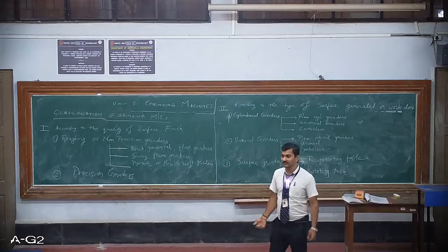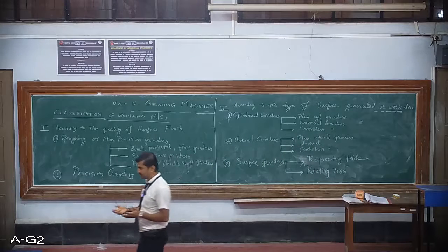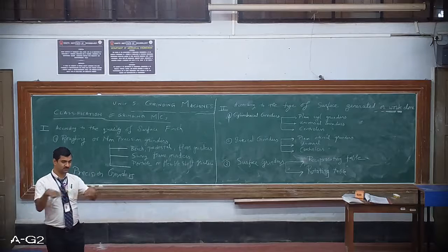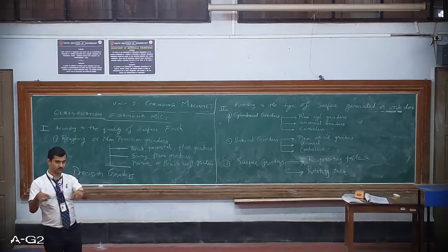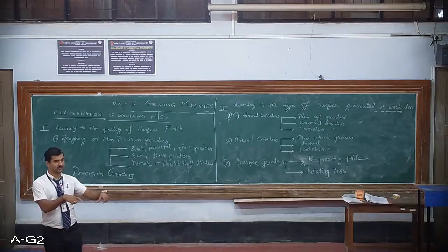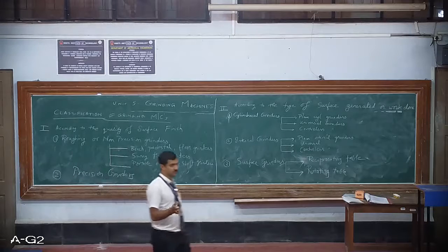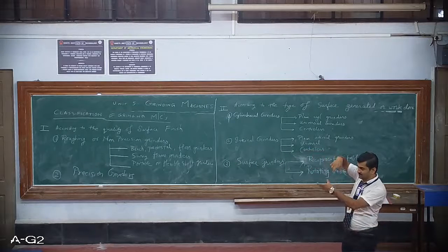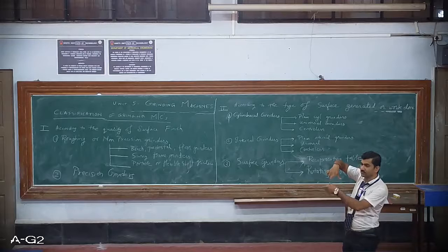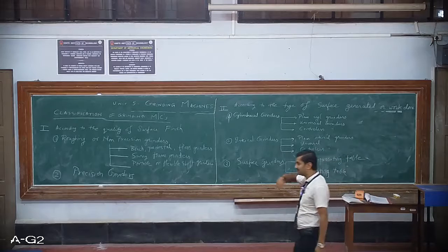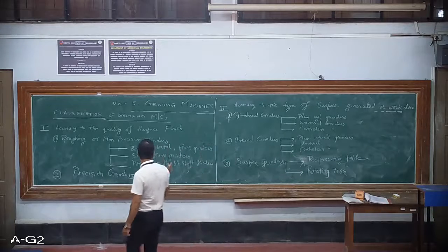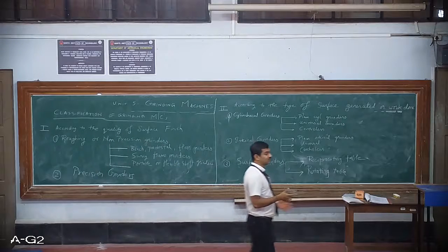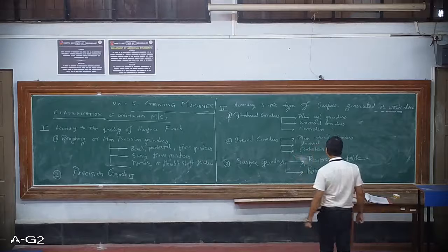Reciprocating table means you have a grinder in which you have a table onto which the workpiece is mounted. The table is continuously reciprocating. It will move from one end to the other and reverse. So that is reciprocating. You know reciprocating motion. The grinding wheel is fixed from the top, the table reciprocates, and the grinding wheel is brought in contact with it, right? So the material is removed. In the rotating type, you have a rotating table on which the grinding can be performed. The workpieces can be fixed at different places. So that is the classification.